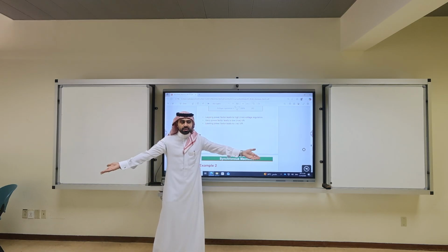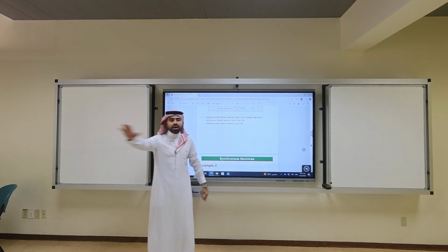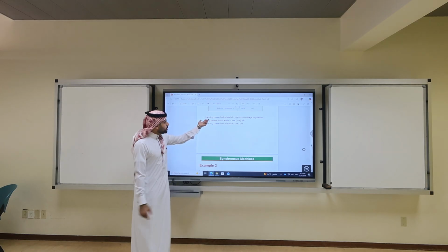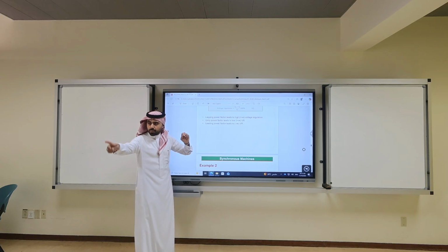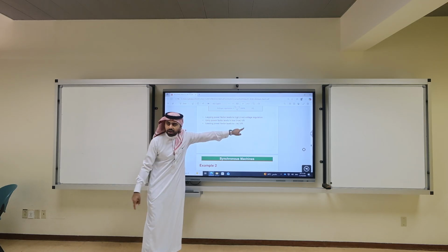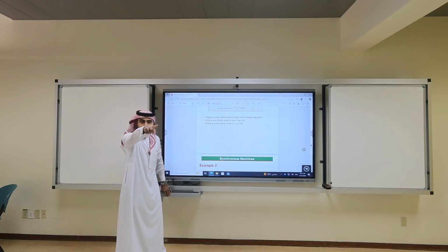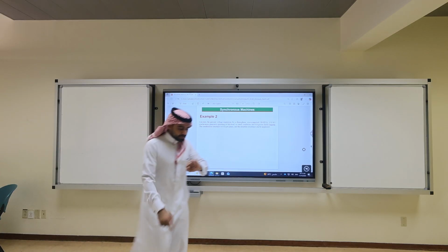You also don't want to be underexcited. There are applications for the overexcited. There are also other applications for underexcited. But the normal generator should be in normal excited mode, which is small positive VR. Clear? Clear? This side. Let's do an example.